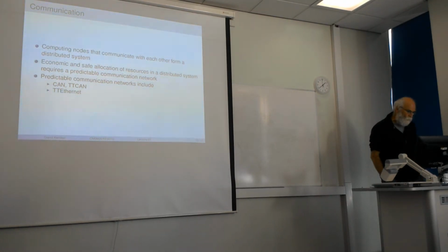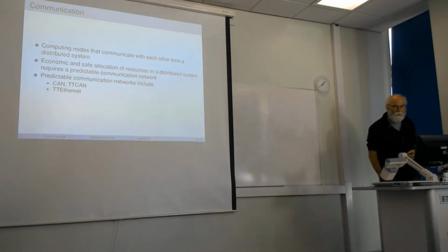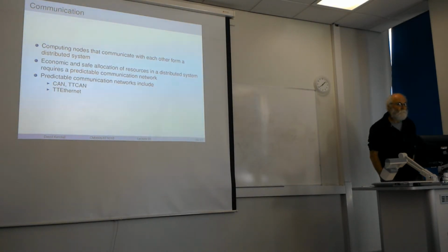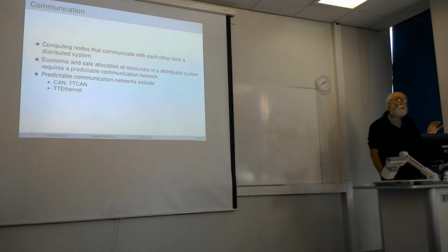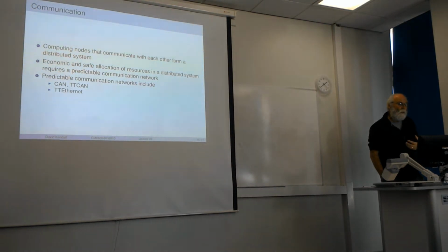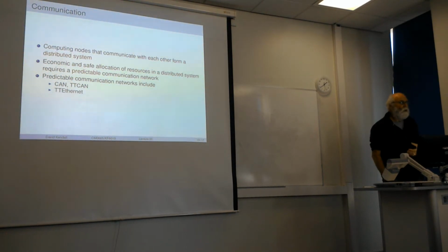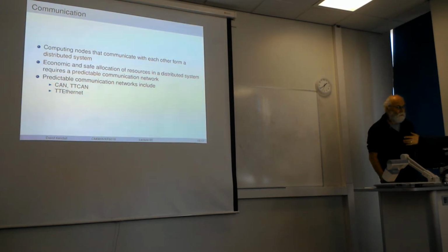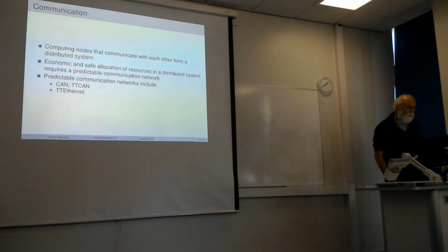and that avoids collisions. There's another bus which is getting a lot of attention currently in the automotive world called FlexRay. That kind of adopts a hybrid approach, if you like. So some messages are time triggered with guaranteed predictable delays, but some messages are allowed to be what you might call best effort, in which the need for predictability isn't strong, and so we can just make use of any remaining bandwidth in the network for sending our best effort messages.